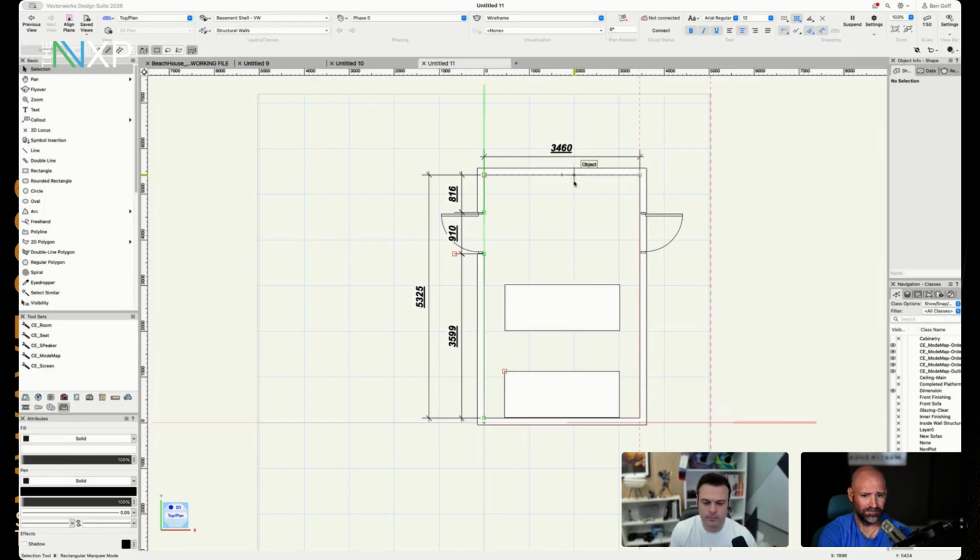So low frequency energy builds up against those solid boundaries. If I put a seat against that back wall, I'm going to get an excess of bass, and there's almost nothing I can do about it because that bass is going to build up. We did do a full video on that which really explains it in depth, but it's going to be a problem.